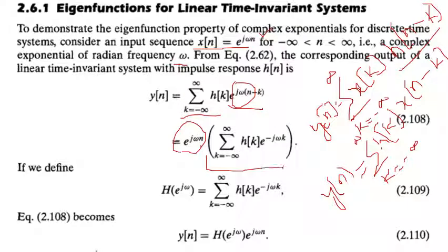Now the rest of the expression is the formula for the Fourier transform, or the formula for calculating the frequency response. Why do I say this is the formula for the frequency response? Because here we have the impulse response. If we have the impulse response here, we can calculate the frequency response. If we have an input signal here, we can calculate the Fourier transform of the input. So this is the formula for finding the Fourier transform of the impulse response: the signal in the time domain and then the negative phasor. So this is the frequency response.